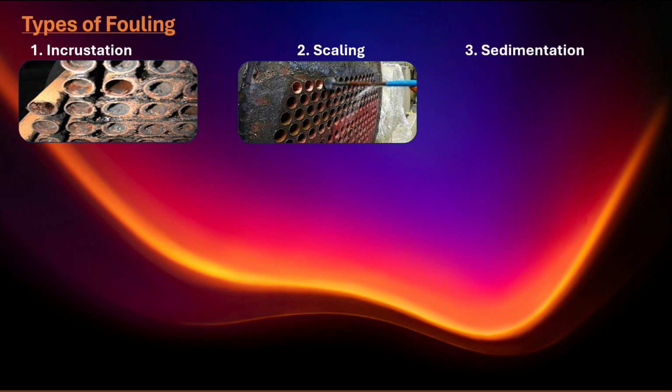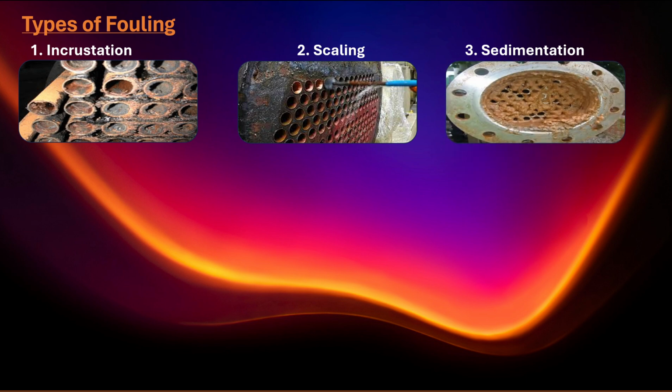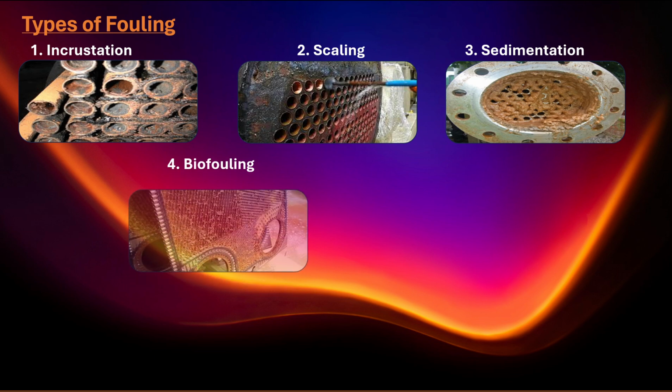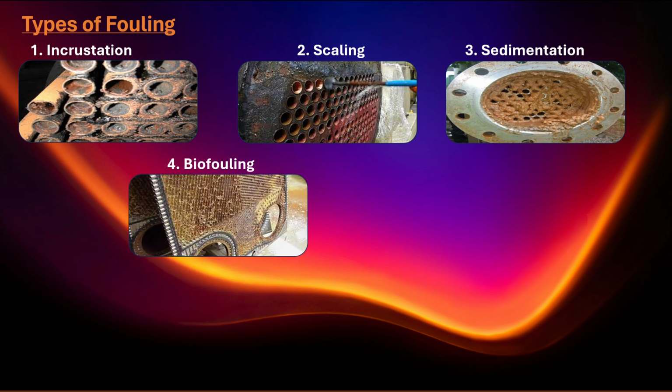Sediment, particulate fouling: deposition of suspended particles like corrosion products, metal oxides, silt, alumina, microalgae, and their excrement, which block flow paths and impair heat transfer. Biological fouling: growth and attachment of microorganisms such as bacteria, nematodes, protozoa, and sometimes larger marine organisms, forming insulating layers.